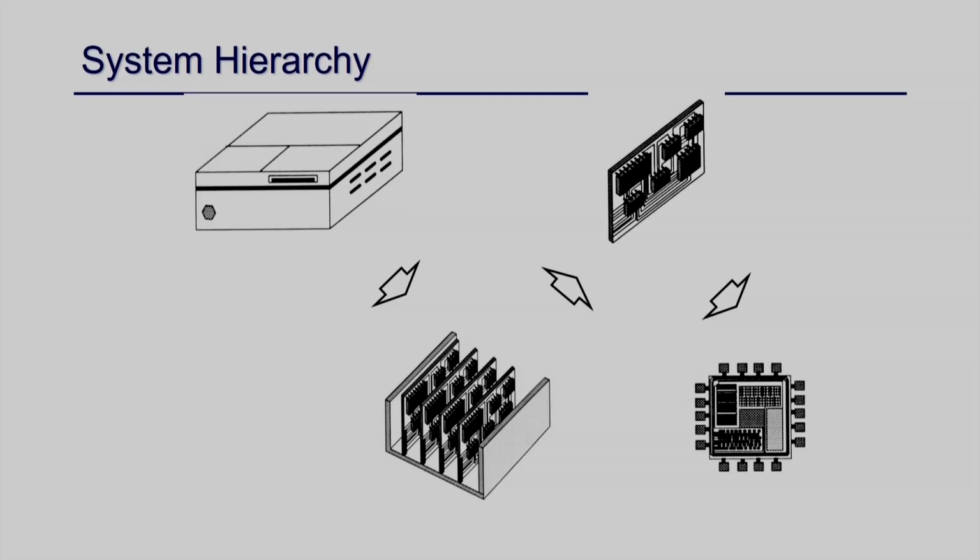So partitioning is something very common in every approach, right. If you just think about ASIC prototyping, what we actually do is, we have a big system, right. This might be a HAPS board, where we stack multiple FPGAs, right.